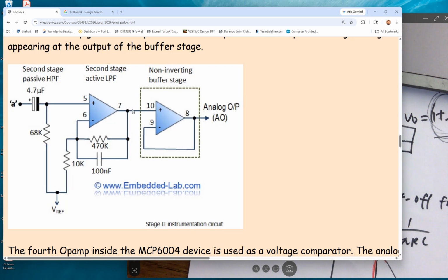Imagine that if you directly connect the resistor here to ground, what's going to happen? This resistor won't be 430K anymore, right? It's being affected. You got a current going through that resistor. So you have a super high input resistance. This could be considered as a disconnected circuit. So the following circuit is not affecting whatever the resistor connected to the front stages over here.